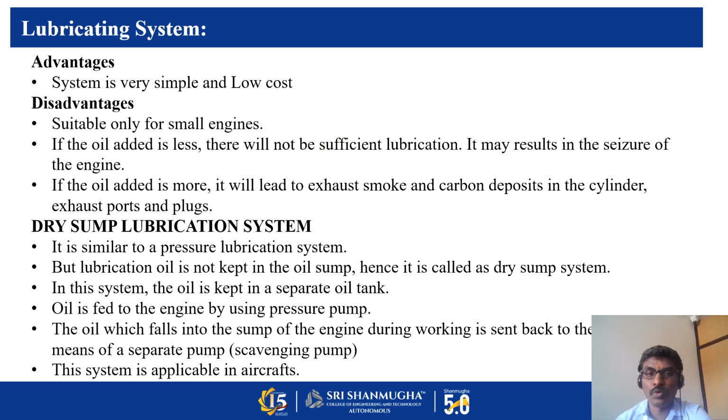Disadvantages, suitable only for small engine. If the oil added is less, there will not be sufficient lubrication. It may result in the seizure of the engine. If the oil added is more, it will lead to exhaust smoke and carbon deposit in the cylinder, exhaust port and plugs. Dry sump lubrication system.